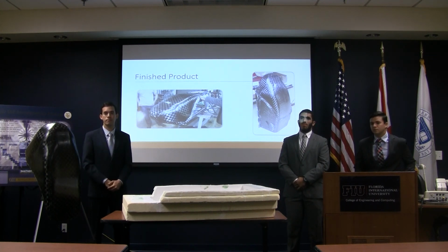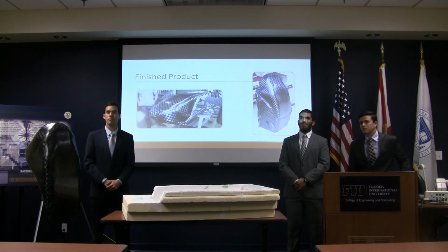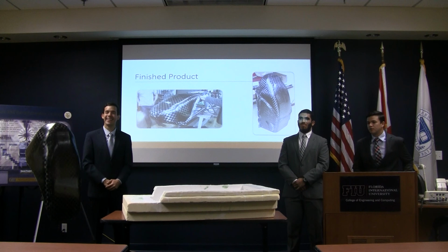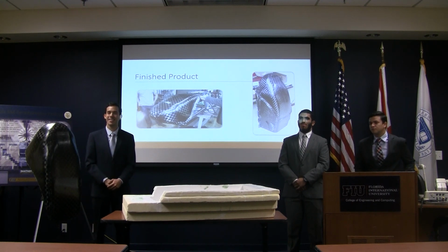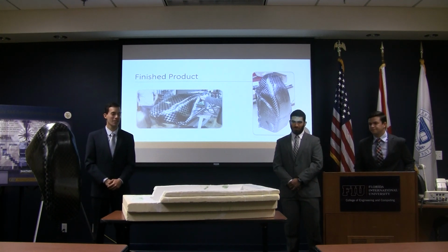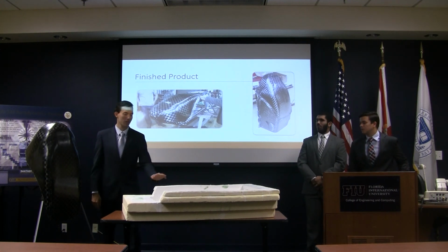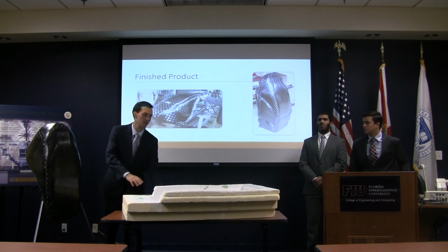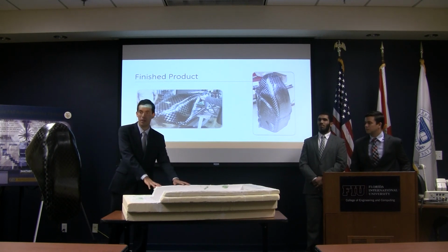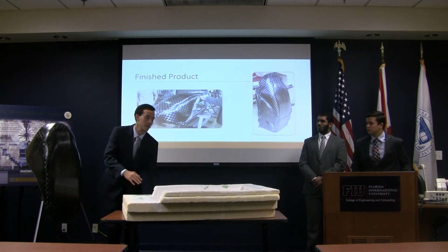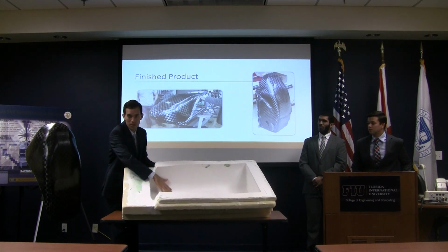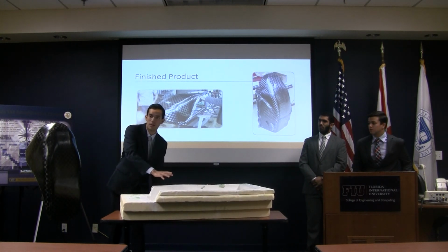Okay, thank you. To ask a little bit about the vacuum bagging, you showed that, but it looks like a pretty complex process. It's a long process. I don't know much about it. I see boat builders use it all the time. I'm just curious how you guys did it, vacuum pump and plastic bags. Yes. So before the vacuuming process, the first thing is to have the mold complete. After you have the mold completely sanded and smooth, you have to wax the actual mold.